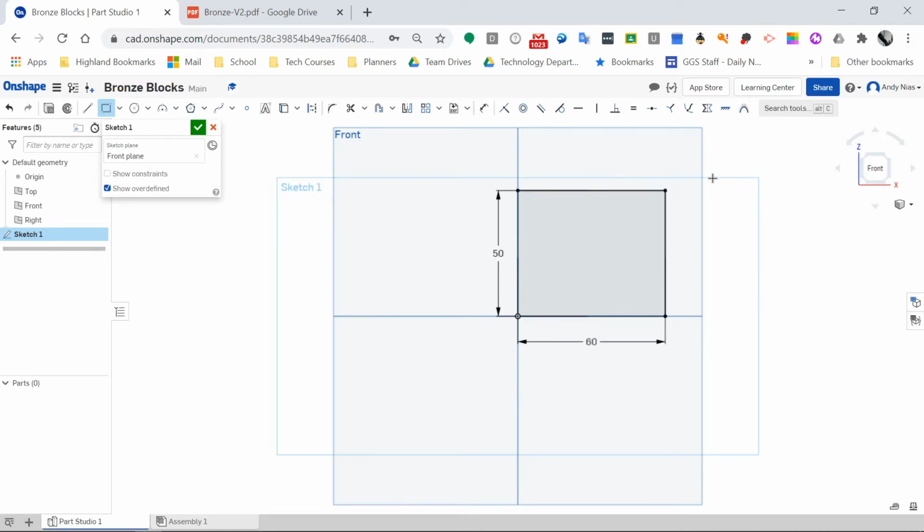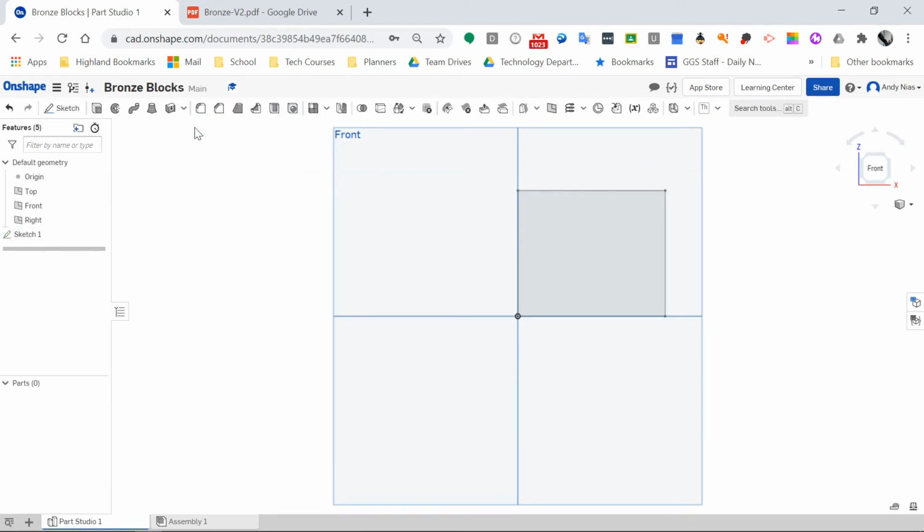If you make a mistake at that point, I'm just going to right click my mouse and escape the rectangle tool so I get this cursor. I can now select parts of my sketch, so I can hover over and select that number, and if I wanted to I could change it to correct it if I made a mistake. Okay, so same with the other one here. That is now the right size, so we need to finish that. We're going to tick, yep, sketch is done.